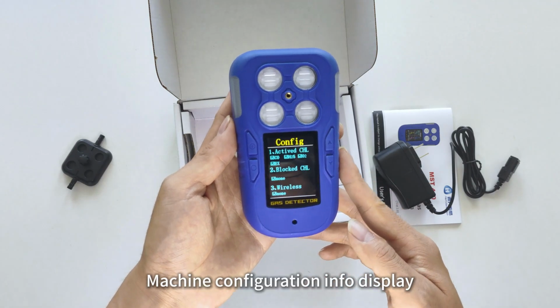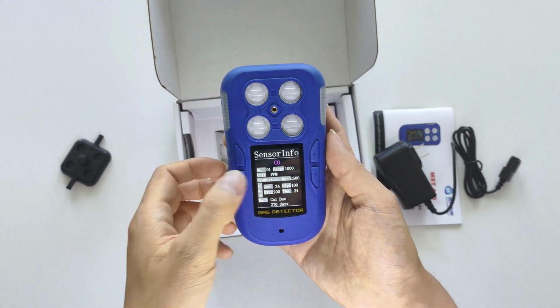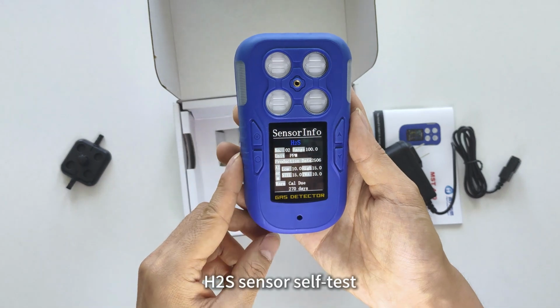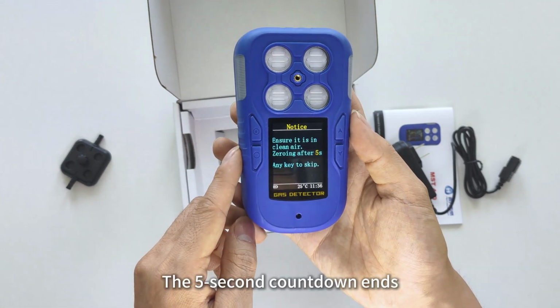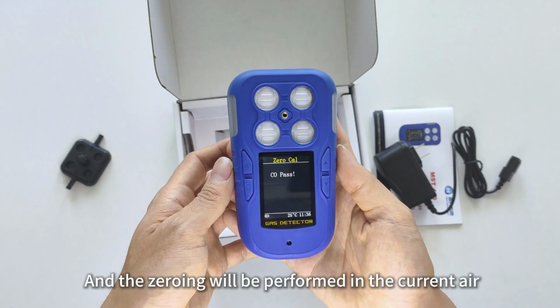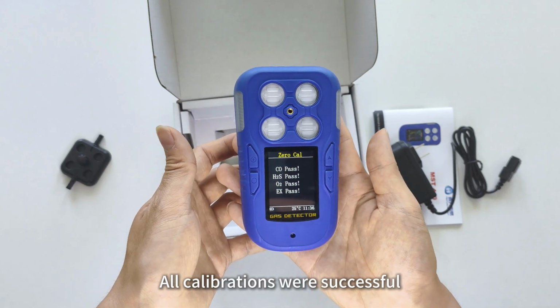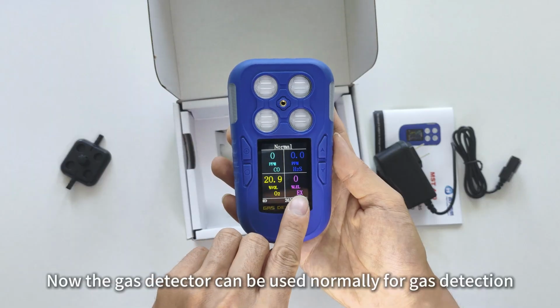Machine configuration info display. CO sensor self-test. H2S sensor self-test. O2 sensor self-test. X sensor self-test. The 5-second countdown ends, and the zeroing will be performed in the current air. All calibrations were successful. Now the gas detector can be used normally for gas detection.